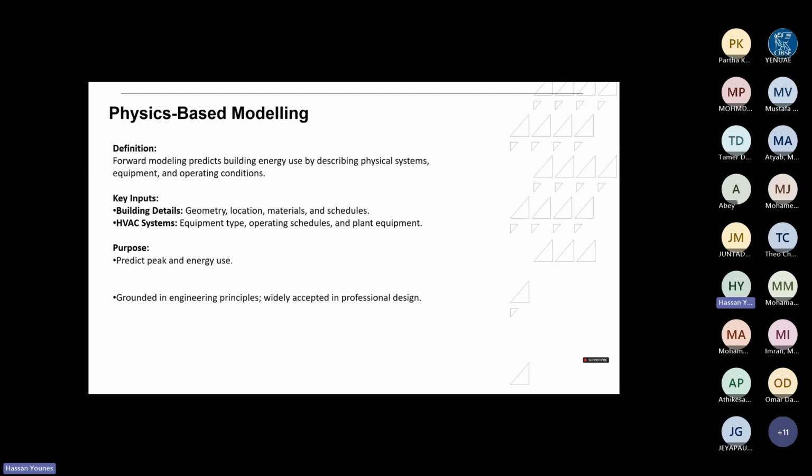Now, in our region, peak is not as important at the moment from the tariff point of view. If you look at your tariff, we don't pay for peak energy. Compared to the US or Europe, in some states in the US it would be maybe $10 per kilowatt per month. So if we have, let's say, 1,000 kW as our peak power during that month, we'd be paying 1,000 times 10. That's $10,000 for that specific month. So we don't have any peak charge at the moment, but we would need to do that for other reasons, but not for the tariff.